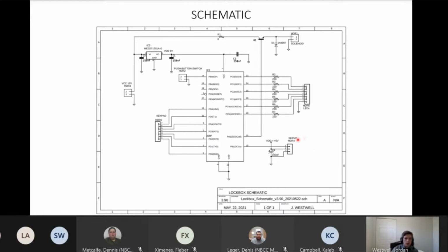The servo motor is a 180 degree rotating servo, and I have it set to basically almost go to the 180 degrees, but not quite, because I didn't want the string or the fishing line that's attached to it to potentially rotate the other direction when the servo motor goes down from its very top position. And up here we have a diode that is a freewheeling diode, just in case there's any sort of reverse current from the motor shutting off. It provides a path for the current to flow through.